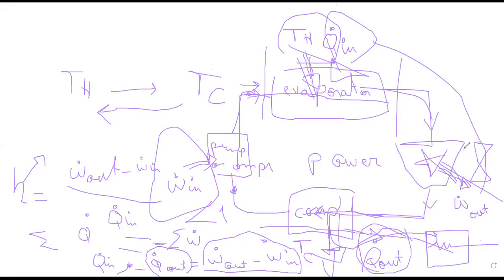This is why I can replace the turbine by an expansion valve, and we'll see together that for the expansion valve I can neglect any W dot out from it. I can consider it nearly zero. It's a device that works at constant enthalpy. So it will expand my fluid while having constant enthalpy, so H in equals H out. And therefore, in this system, I was able to displace heat from a hot to a cool environment by providing work.